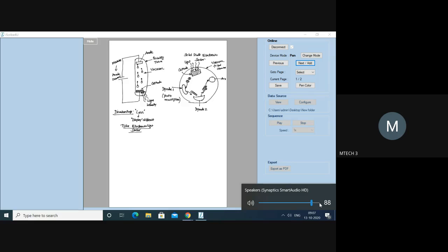These secondary electrons liberated now will go towards the anode. Without the dynodes, just as an example, only two electrons were supposed to go to the anode, resulting in a lesser amount of anode current. Because of the presence of the dynode, which acts as the photomultiplier, more secondary electrons are liberated. You can have as many dynodes as possible, so that you get an appreciable amount of anode current. Then you measure the anode current, which is the intensity of the light.